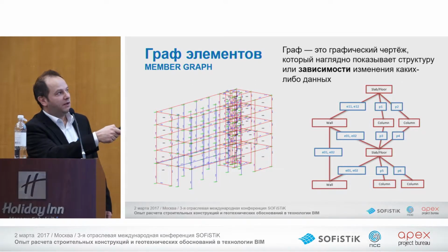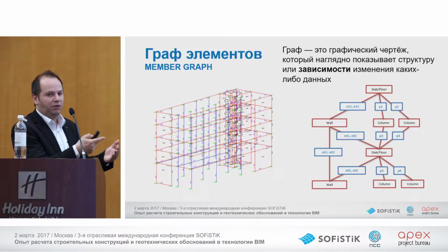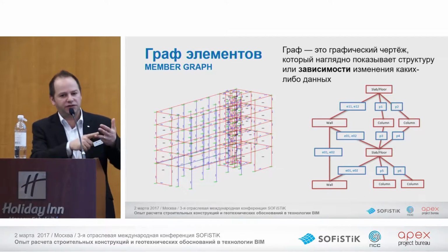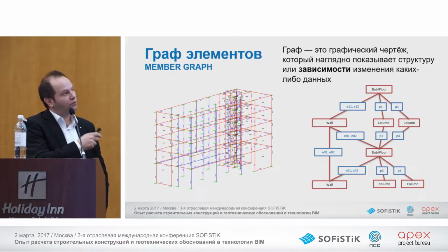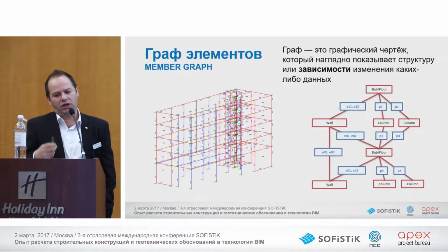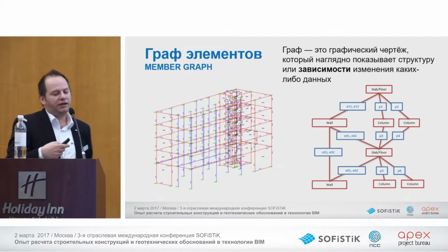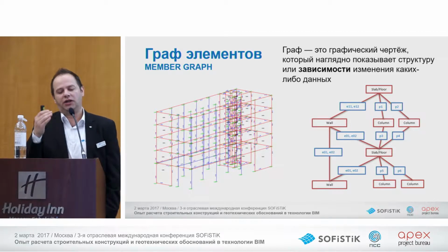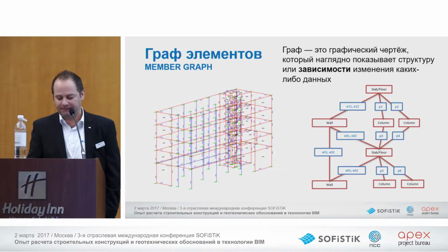The floor maybe is supported by some walls and some columns, and we have to define the connection between these elements. In a normal analytical model, this is defined by hinged or fixed connections or something like that, or also a non-linear connection between them. This tool, which we call Building Manager, should give you an overview of the connections between the elements. And in the next slides I will also show you that you have the possibility to change that connection, or to change the load takedown of these simple buildings.